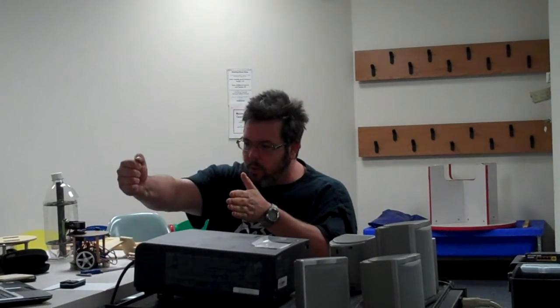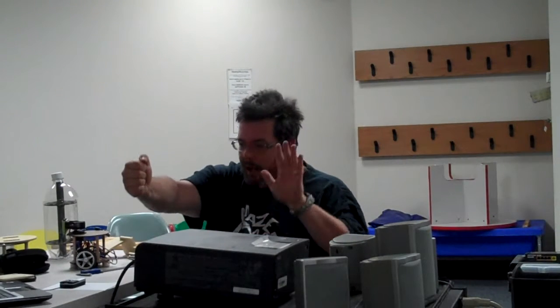So, like I said, unfortunately I couldn't bring my machine in and show you that, but that's really all it is. So you just do a file, open the NC file. I have to bring my cutter head to a certain point and say home. So that's my origin point, right? Remember we talked about that earlier. I have to home it at the origin point, and then I just come up here and click the play button, and off it goes. And then hopefully remember to turn the cutter head on, because otherwise it'll snap it off again too. So really, that's it. This is probably the simplest part of it. Once it's all set up: file open, home, and then play.